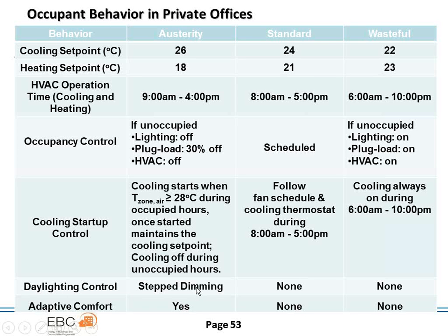And then, of course, the daylighting: are you turning off lights when you have enough daylight? Also, for example, in the ASHRAE standard, there's a comfort model. Its basic theory is that when outdoor temperature gets higher, your indoor comfort temperature is also higher, based on, I think, surveys of naturally ventilated buildings. But they are pushing this for mechanically cooled buildings too. That's the argument over whether that's still applicable.